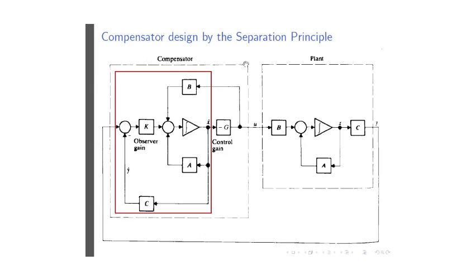And that is why the compensator boundary is there. Think of it like this. The compensator is really what you, as the control engineer, add to the plant in order to control it. And because of that, the compensator needs to include the feedback gain that we've designed in chapter 6.